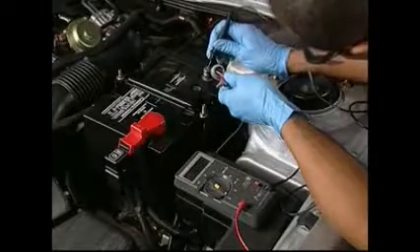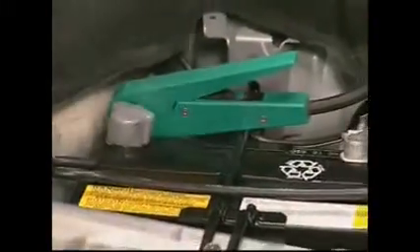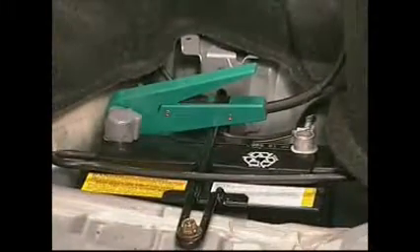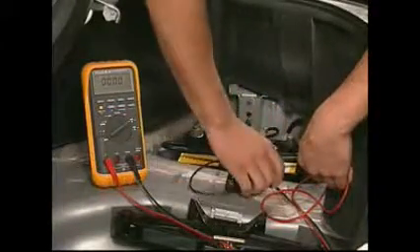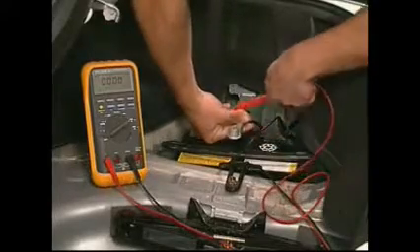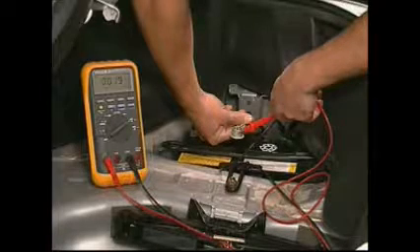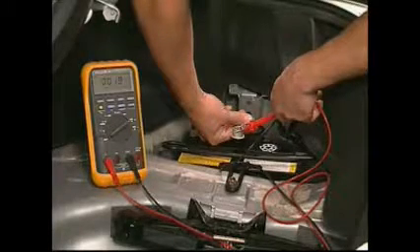Since an ammeter must always be used in series with an electrical circuit, an inductive probe will save you time because it allows you to make your tests without opening the circuit. If your meter doesn't have one, then you'll have to disconnect the negative battery cable to put the meter in series. There are a few precautions that must be followed prior to doing a parasitic draw test with an ammeter.